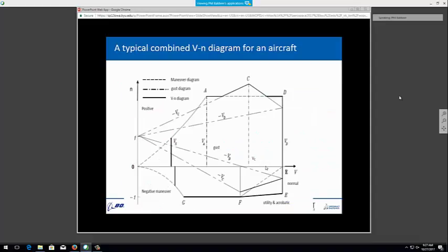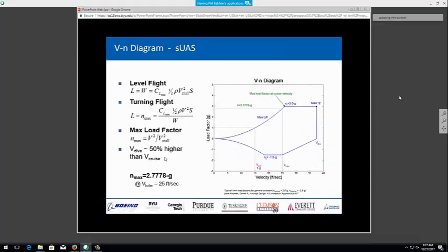Okay, so obviously the hand launch is an extremely important element of the design, and our previous constraint relationship, where we're kind of modeling it as a short takeoff, is not really the best approach. So one method would be to do a more simulation-based approach. In this case, it's a very simple Excel model I built in like half an hour, where the assumption is that you are flying at a constant CL. I label it CL max, but really, as soon as it comes out of the hand, it stays at a constant CL, and that's defining the lift force. And thrust is also constant, and that's defining your forward acceleration.